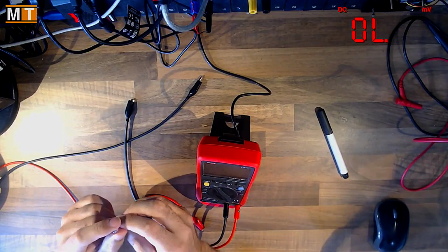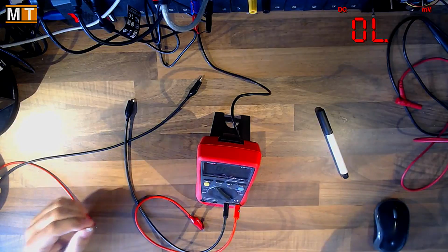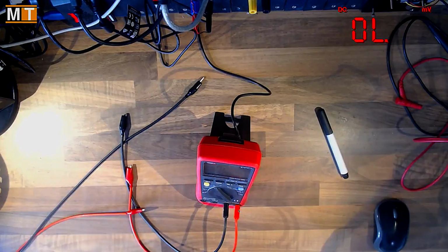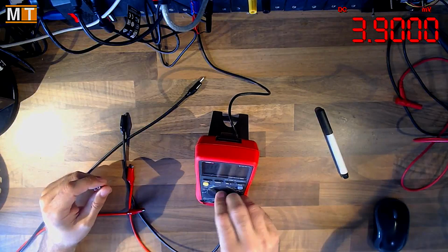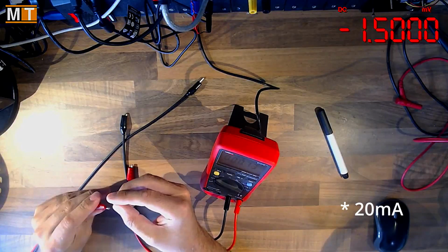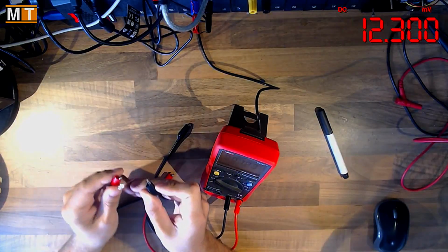Also, you don't want to provide too much current. Now, the LED being a non-linear device will limit the voltage. Let's bring my power supply into play. I'm going to set the voltage to 5 volts, but the current limited to 20 milliamps. So this has got 5 volts, but the power supply is limited to 20 milliamps. Any guesses what will happen? 5 volts directly across this, but limited to 20 milliamps.